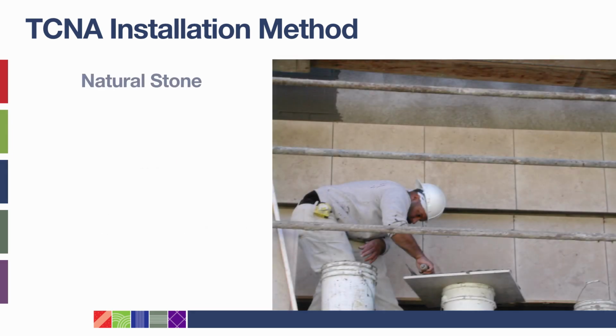You can see in these examples that 100% coverage of the substrate in the natural stone installation can be achieved by using a method known as backbuttering. This method involves applying mortar to both the backside of the tile and directly onto the wall or floor itself. This facilitates fresh material contact for better bond and helps to fully embed the mortar into the tile for 100% coverage.